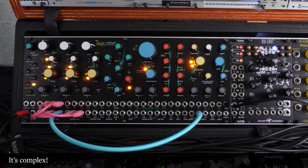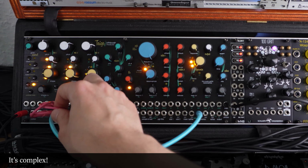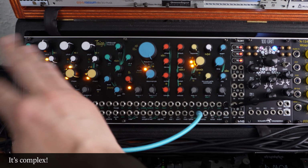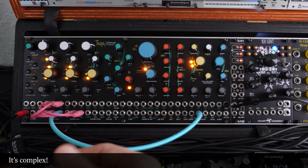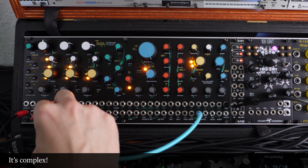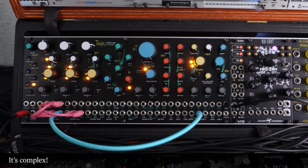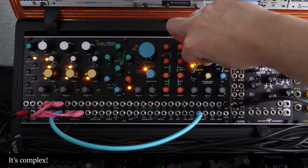But of course, you can also use the Taiga as a complex oscillator. I'm using the output of oscillator 2 to FM modulate my oscillator 1. There's a few small other things that I'm doing. I'm using the sine output of my oscillator 2 to control the shape of oscillator 1. And oscillator 2 is also hard synced to oscillator 1 using this cable here. You get quite aggressive complex timbres out of this, just something like this here.